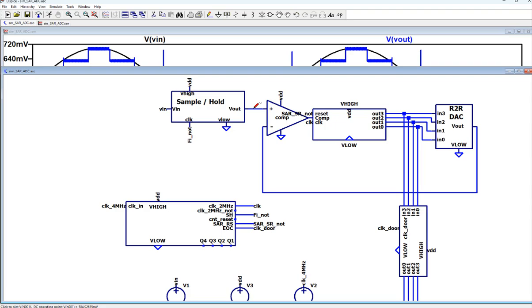So I think it's okay if you have this one here first, and then we wait for another cycle. I'm going to show you a technique over there to save some time. But if this is ready, being held there, sometimes, just in case it's not very stable right after the falling edge, we probably need some hold time over there before we compare it with the 1 and all zeros, right, at the first cycle. So it's okay. Have the data available over there, analog data to be sampled and held over there is ready.